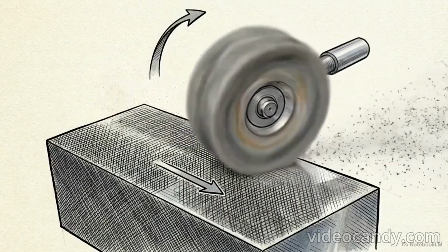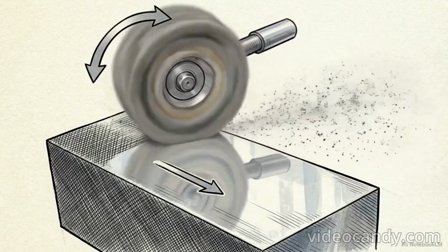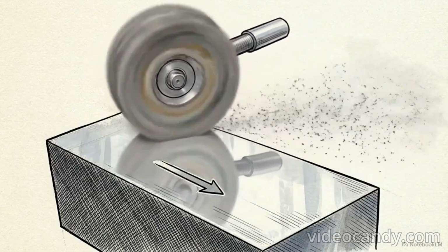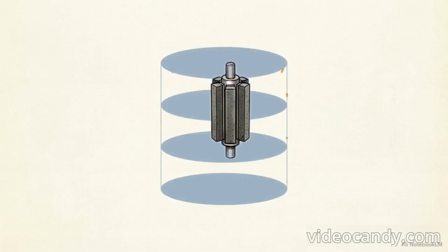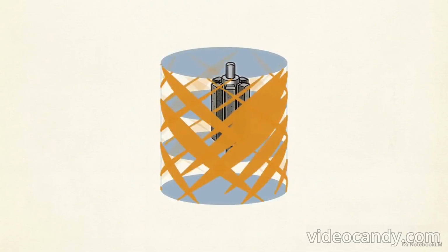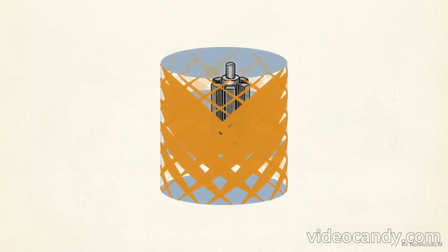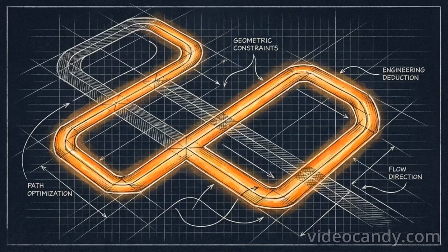One primary method is lapping. This involves trapping a loose abrasive slurry between the workpiece and a softer lapping tool. The friction slowly wears down those microscopic high points until the surface achieves extreme optical flatness. Lapping flattens, but polishing smooths. Polishing utilizes fine abrasives mounted on flexible backing wheels to buff out microscratches and achieve a specular, mirror-like finish.